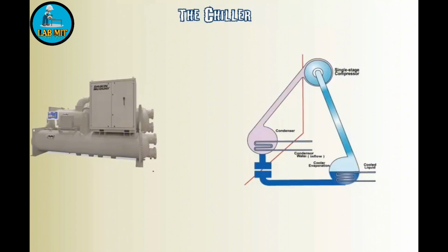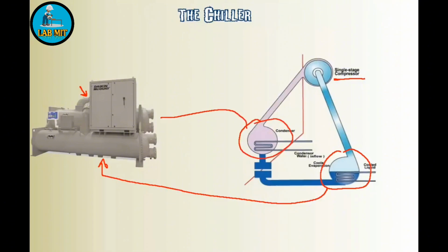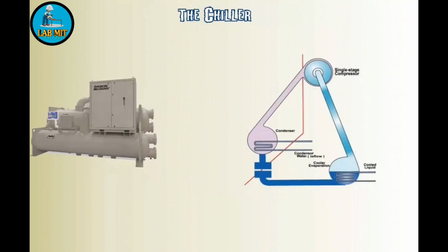Very simply, they're the compressor, which is right here. And also mounted back here on the back side where you really can't see it is the compressor. And then you have an evaporator section, which is typically the bottom barrel here, and the condenser section, which is your upper barrel here. These 3 pieces are the main parts to a centrifugal chiller. Now there's many other facets and refrigeration cycle and all that good stuff, but as a controls freak, I don't spend too much time on that kind of stuff. There's a lot of resources out there. What I concentrate on is bringing the systems together and actually controlling them to do what they're designed to do.